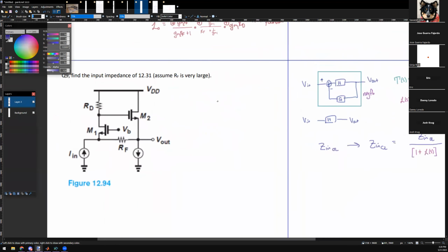In case there was a voltage input source, then we had to multiply it, correct? Correct. If the input was a voltage source for some reason, then the circuit ideally has very high impedance, so that it takes as much of the voltage as possible. Can you write a little cap next to it with voltage? Well, I'll be honest with you guys, my cheat sheet says it here. If the input is a voltage source, you want the input impedance to be high. If the input is a current source, you want the input impedance to be low.